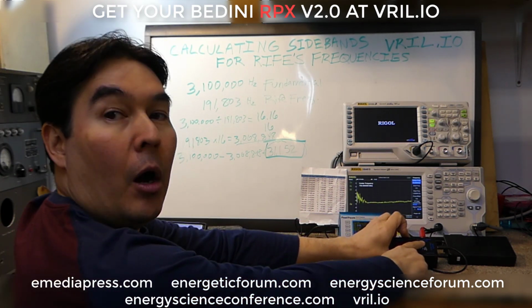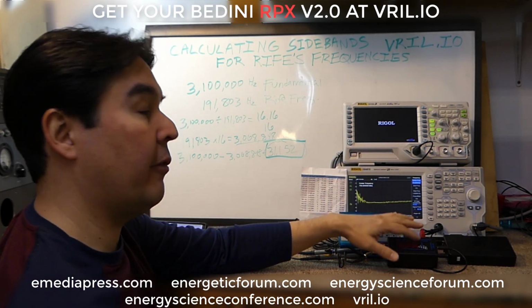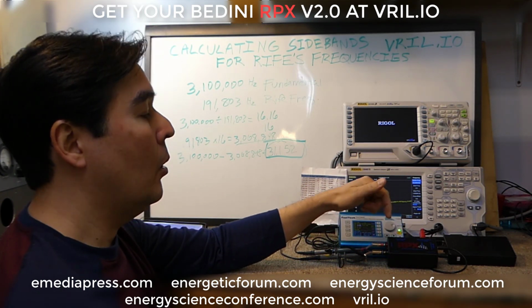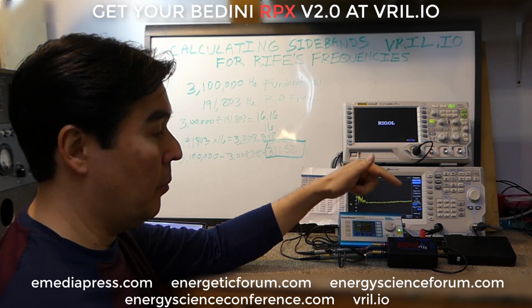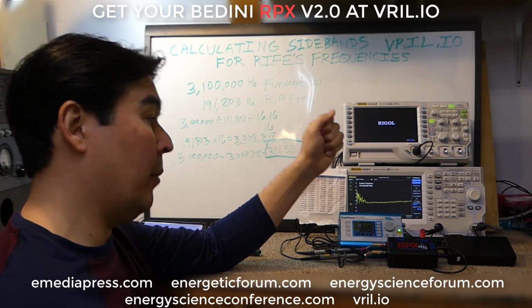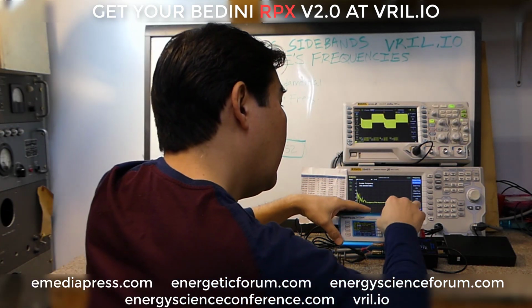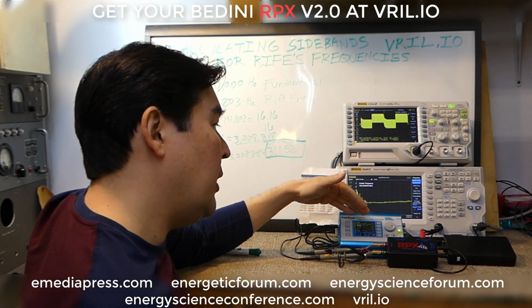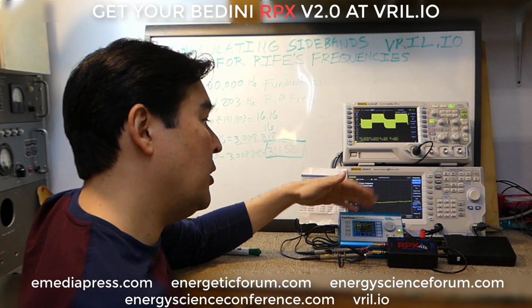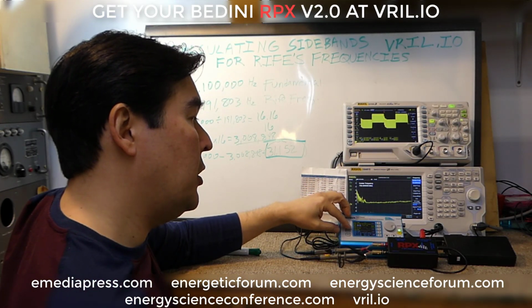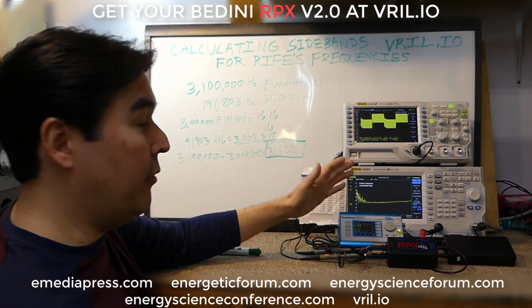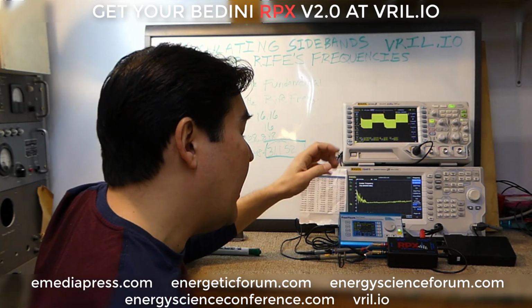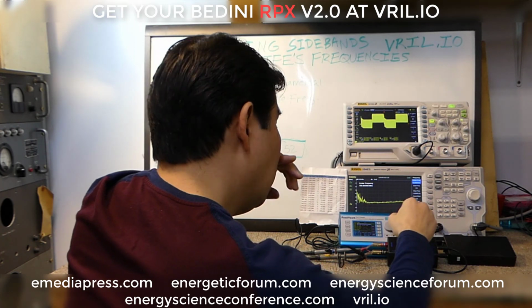It has a little Class A audio amplifier circuit in here to amplify that before it's mixed with the fundamental, before it goes into a RF amplifier chip. Okay, so 2.1 volts, no attenuation, no phase angle change. This is a power factor deal, no duty cycle, duty cycle 50-50. And then sine wave, we're going to change this frequency.